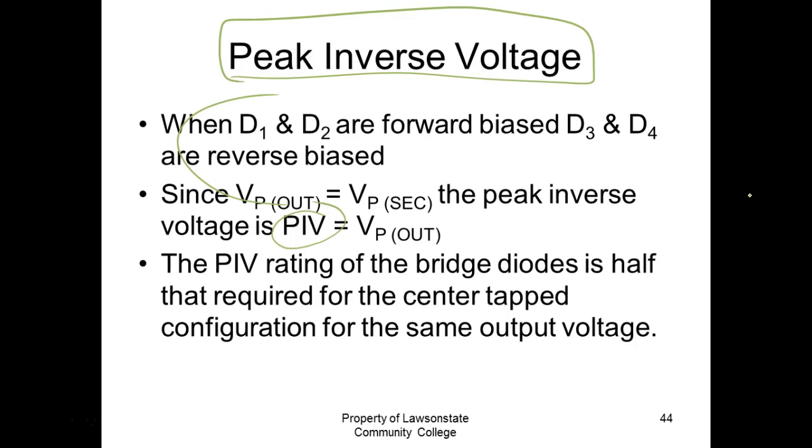A passive device is a device that you can't change its conduction characteristics with bias. So we can't change the conduction characteristics of a capacitor with bias. It's fixed in. It does the same thing no matter what DC level we put on it, no matter what AC level we put on it, right? Now it does vary its opposition, but it does that according to frequency, right?